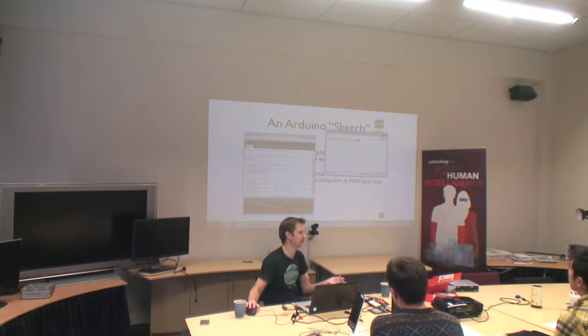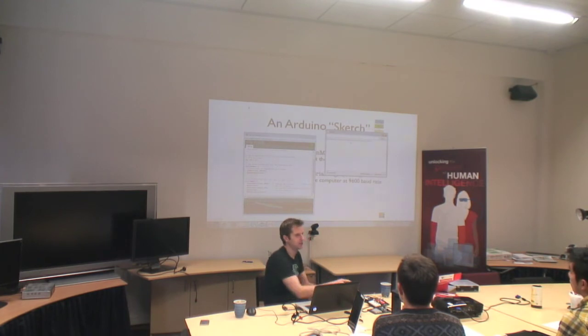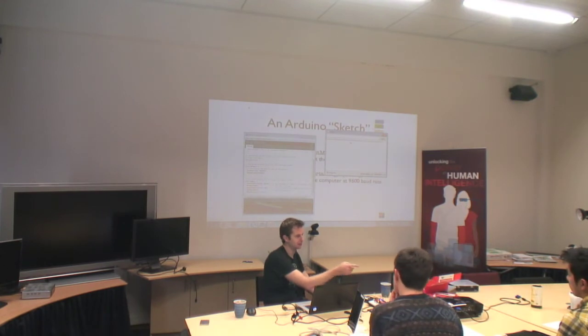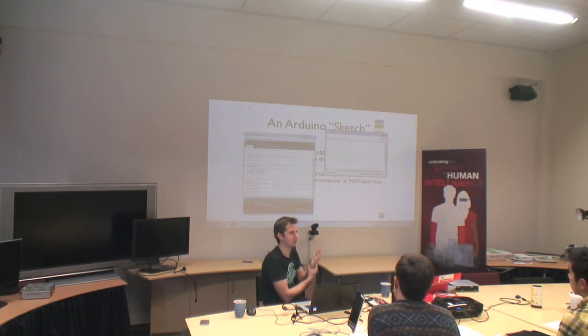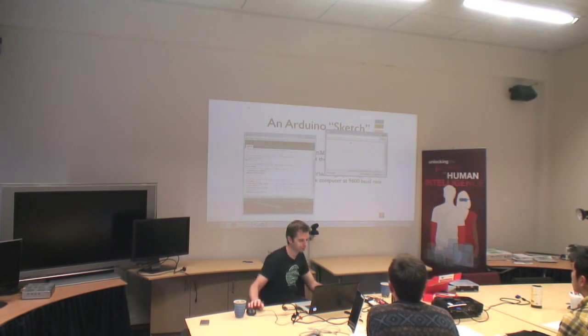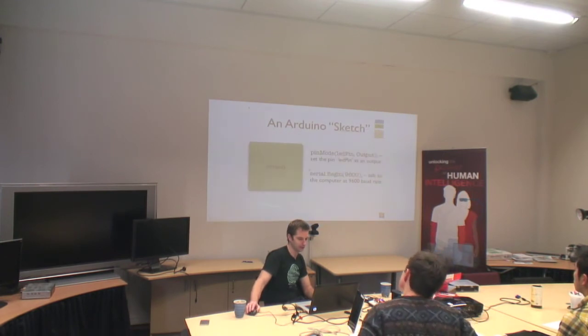So you can see now we actually have this communication going from the Arduino back to the computer, which is kind of nice, because now you can imagine if you wire up buttons or sensors or whatever, now you can actually send that data from the Arduino back to the computer, and then have the computer do something with that information. So you can make your own game controller or wearable device, where you wear something on your hand with some flex sensors, and then you can read those values and do something with it on the computer. So you could make a computer mouse or a game controller or whatever with the Arduino, read the buttons, and then send the results to the computer using serial begin and serial print and so on and so forth.